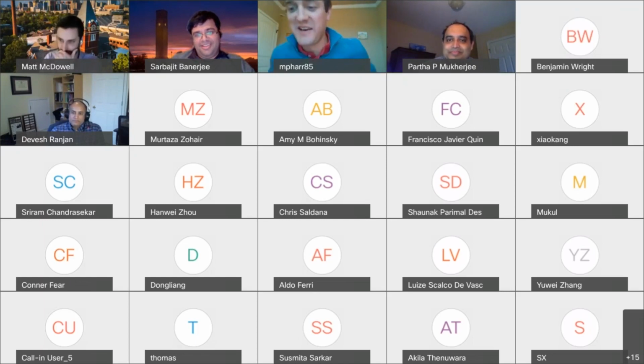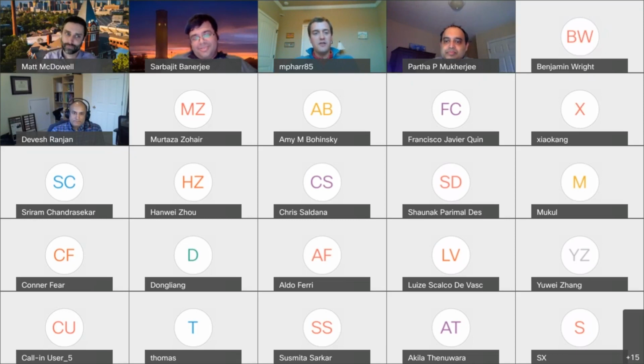Well, one thing, maybe this is obvious, but these things are very soft, right? So a lot of the initial models are doing elastic analyses, which are more or less not very relevant to a lot of real conditions. These things are flowing at stresses that are megapascal or less. If you noticed on that stack pressure slide, the stack pressure that actually densified the network of the deposition is below a megapascal. This is relevant because you can't apply infinite pressure to these stacks in commercially viable batteries. So that sets a representative stress scale that you need.